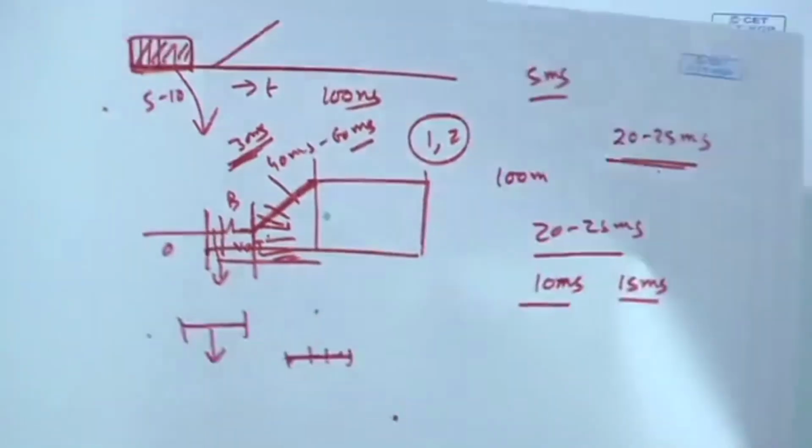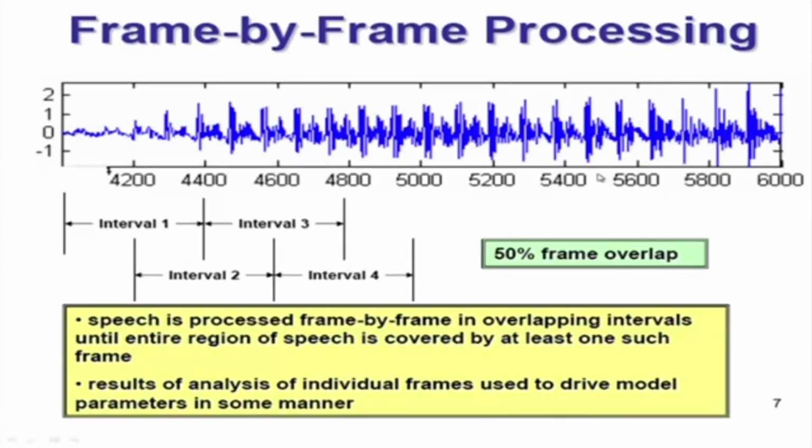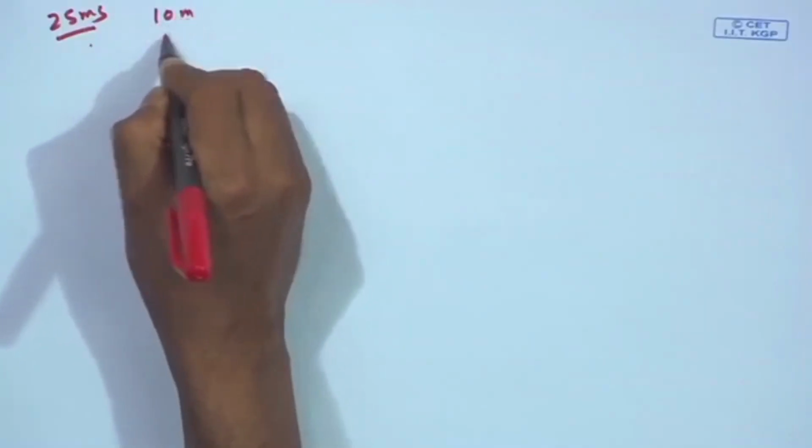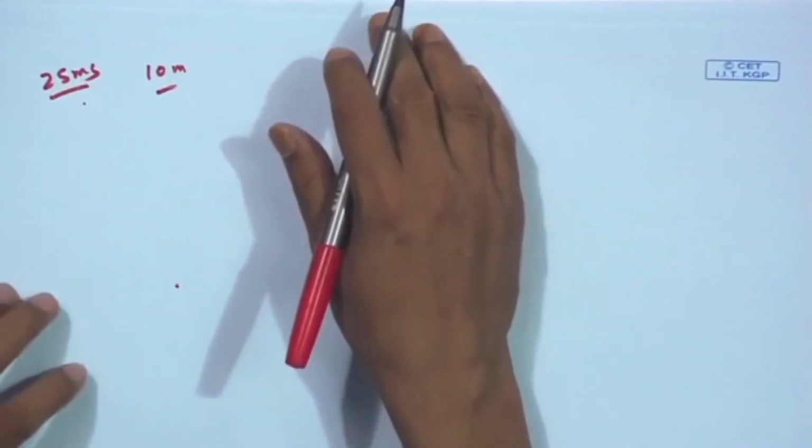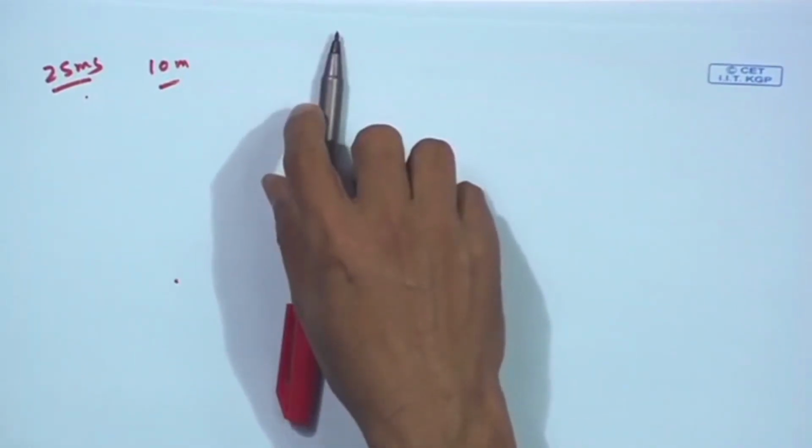Okay. So, now we are framing the speech signal and shifting the window by 10 milliseconds. So, this is the example if you hear. This is the interval 1 and then shifting of the frame by 10 millisecond, or 50% overlap. If it is a 20 millisecond window, 50% overlap means 10 millisecond shifting. So, I get 100 frames per second. I can take 25 millisecond as a window and shift the frame 10 millisecond, that also I get 100 frames per second.